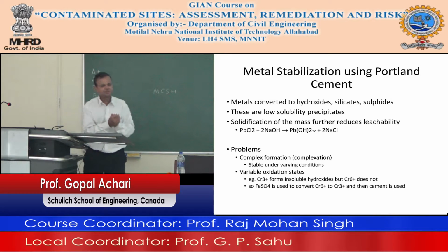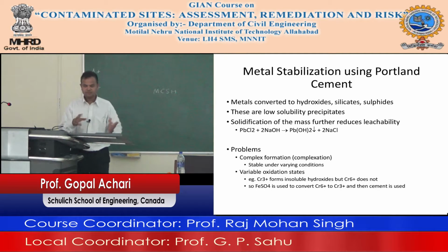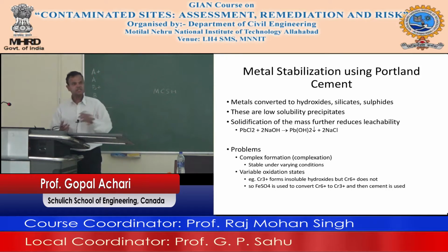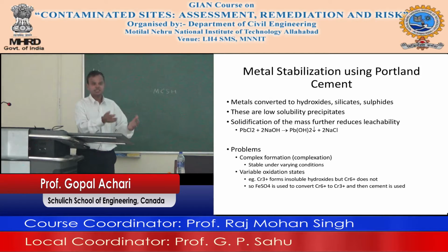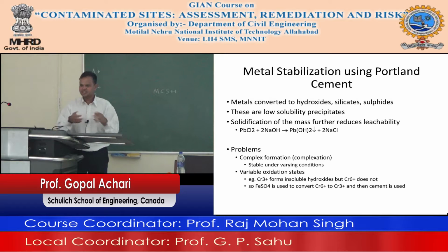If it is sitting on the periphery fixed in a low permeable matrix, then once you solidify, you have to take that stuff, crush it, and put it in a low pH solution and shake it for a period of time to show it does not leach. If it is just trapped in a low permeable matrix, once you crush it, it will go out.